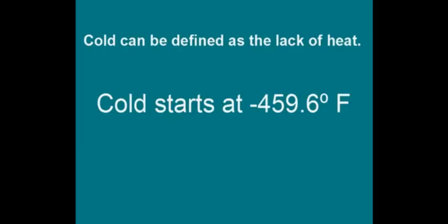The same way that 20 degrees above zero air, a heat pump can extract heat from 20 degree air. All we need is a fluid, a media, a refrigerant that can drop its condensing temperature 10 or 15 degrees below 20, and if we can do that, we can absorb heat from that because hot goes to cold. You'll see that in the next slide. Cold doesn't start until you get to minus 459.6.